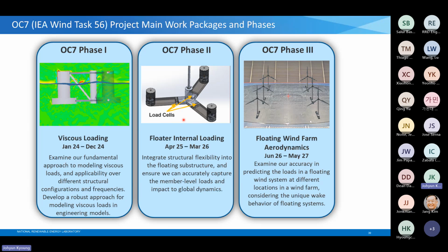You are not scaling the flexibility, elasticity of the structure to real elasticity. It's just a pure rigid body case. And your load cells will measure internal loads, but they should be made as rigid as possible, to not influence the flexible response in a sense. So this wording, I'm not very happy. I already said during one meeting, but okay.